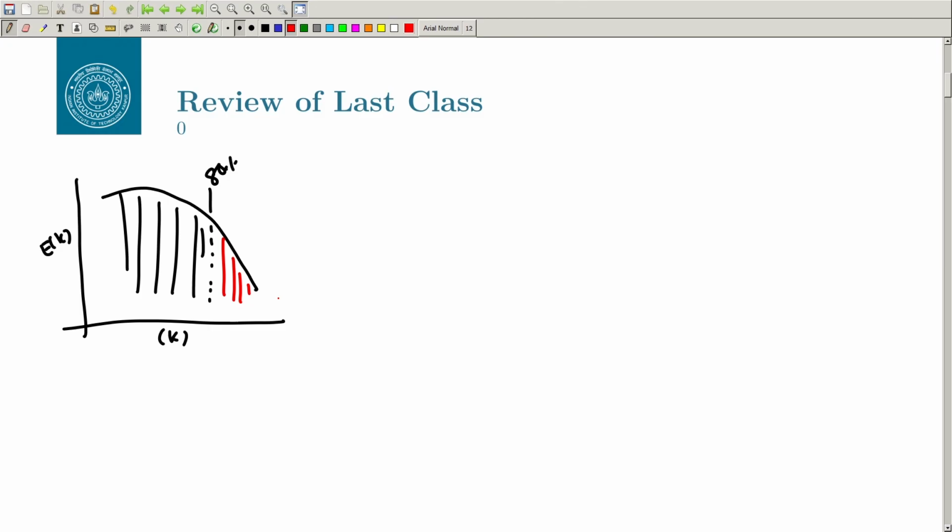So, this is one check you can do if you are performing an LES. We discussed how to calculate the resolved kinetic energy, K_res, and also K_SGS. K_SGS can be directly calculated if you are using an explicit LES; it can be a direct output of the model you are using.